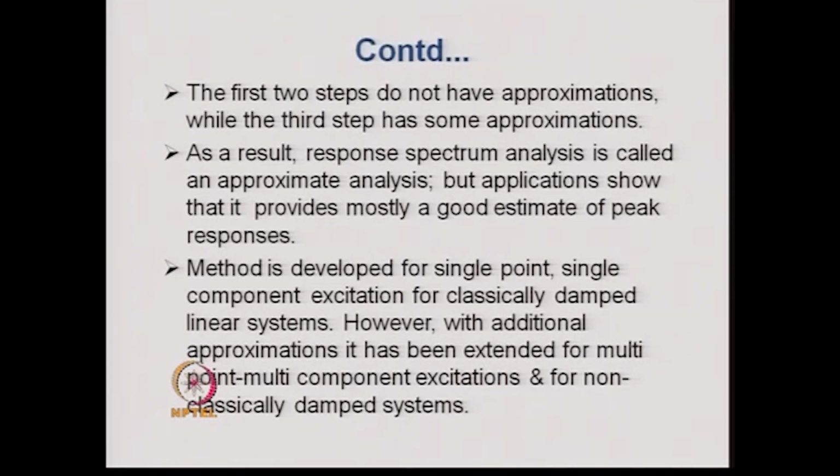When we encounter a structure which is not a classically damped system, like a structure in which two kinds of materials are used, for example, steel and concrete, in that case it no more remains a classically damped system. Similarly, if we consider soil structure interaction in a problem, then also the system does not remain classically damped.